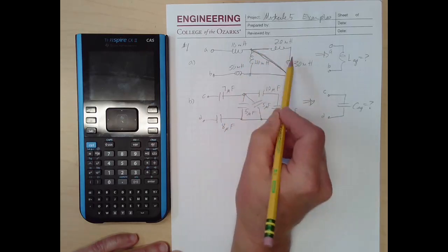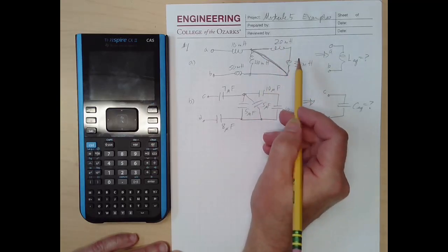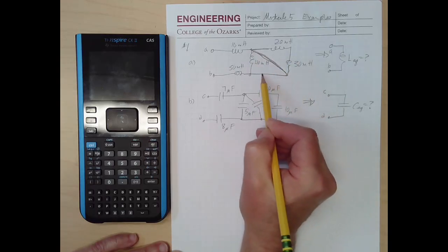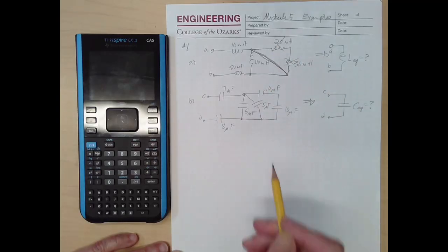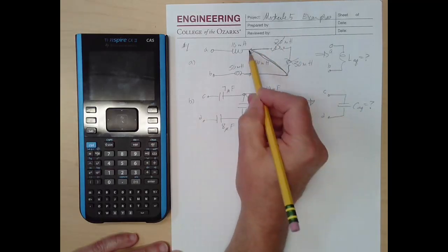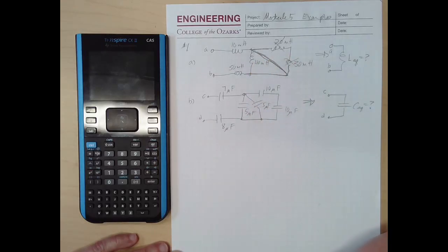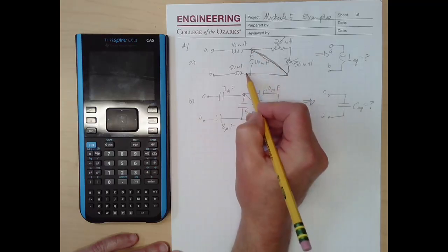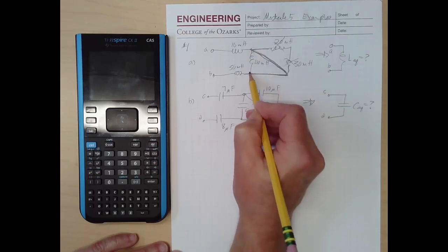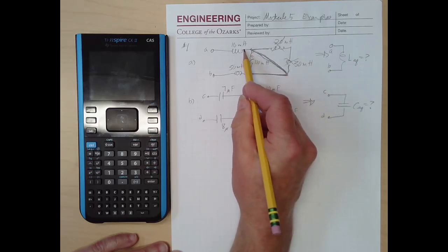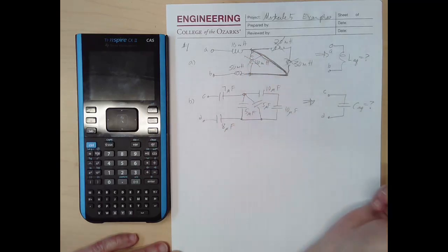None of it will go through those inductors because they are just like resistors. They have resistance to the flow, so they will be unfavored. It'll always take the short circuit path. So these two are gone. They're not even part of the circuit really because they're shorted out. The wire is directly connected across them; they're in series with each other, and end to end the short is shorting them out. Similar story for this 40 millihenry inductor, because again there's a direct path from one end of the inductor to the other. Current coming this way will all choose to go around that inductor. None of it will go through, so that inductor is basically not in the circuit.